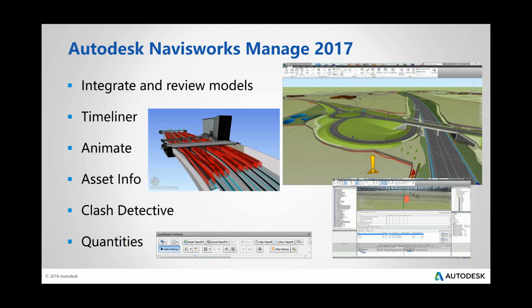So of course, one of the key ones is performing clash detections on the content that's in there. You can quantify the 2D and 3D elements, and really, as I was saying before, one of the other powerful ones that's sometimes overlooked is analysing the model elements, the properties and attributes, really being able to understand what the design intent was behind an element, and us being able to capture that information and share it, so the authors are able to share that with the wider project team.